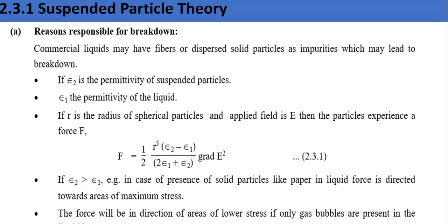So what will be the reason responsible for breakdown? Commercial liquids may have fibers or dispersed solid particles as impurities, which may lead to breakdown. So definitely the reason responsible for breakdown in this theory is suspended impurities, like some fibers of cloth or paper, some tissue, or dispersed solid particles.